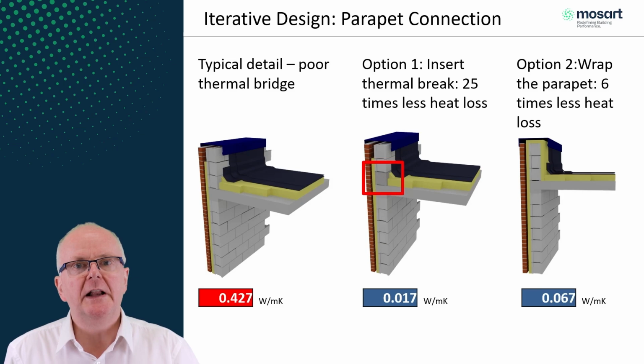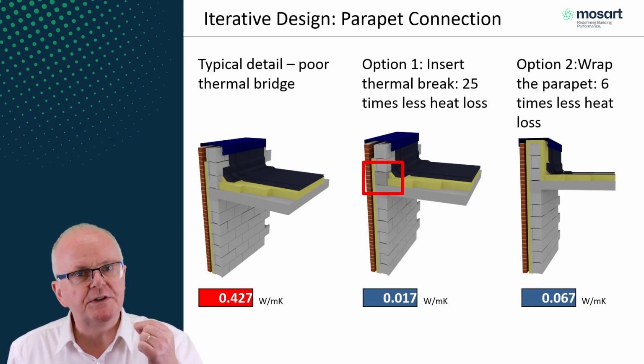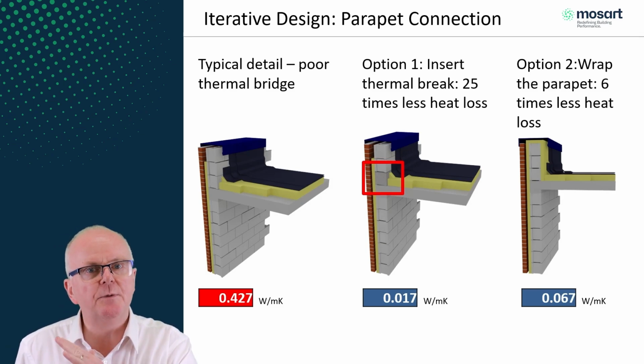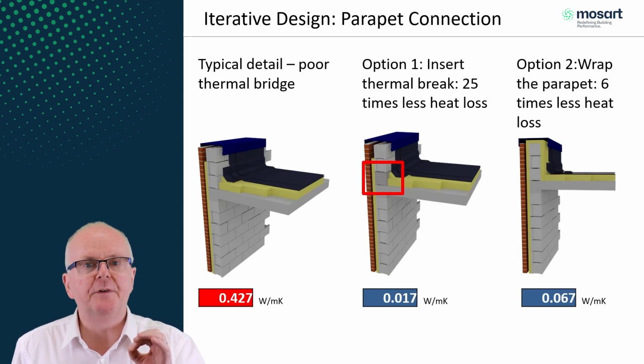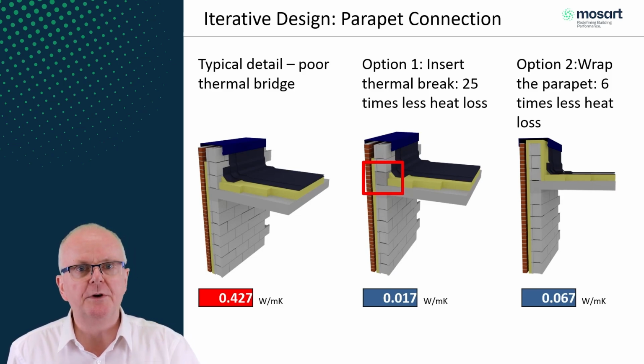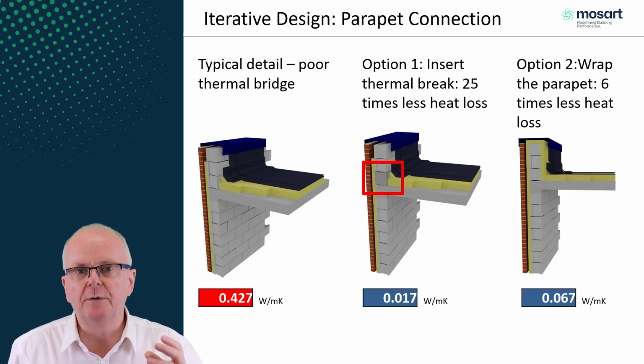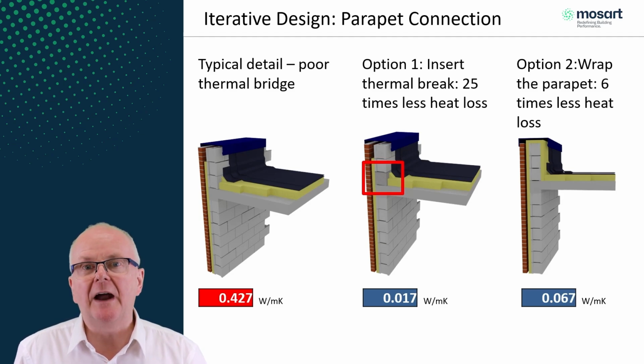Passive House is about honing in on the small things, doing the small things really well, because the big things will look after themselves. But if you focus in on details like thermal bridging, air tightness, all that, window installation details, then honestly everything else will follow quite well. With regards to thermal bridging, parapet details are often forgotten about. We tend to focus on other stuff, but not in Passive House. We've got to pay attention to every detail, every junction, every interface of the different planes.